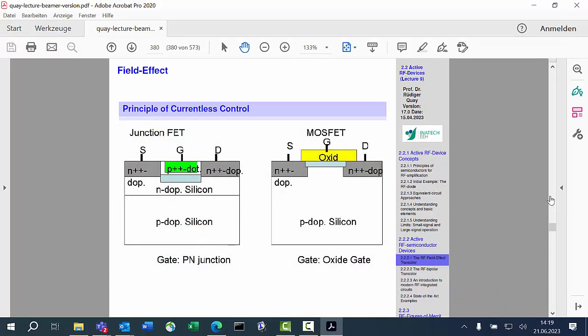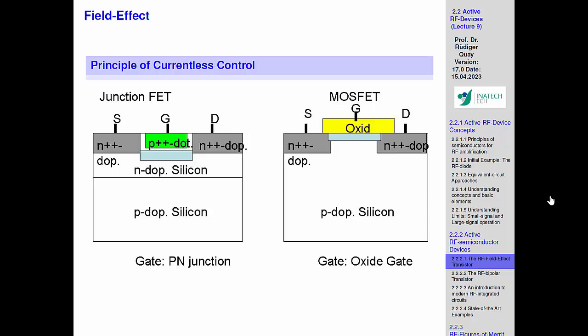So with a junction FET, you will have trouble in reaching the speed of microwaves at all. That in itself is important. So the MOSFET only works because of the MOS gate. That's the principle, because the moment you put in a current, then you're in trouble. It's important that you understand that part.